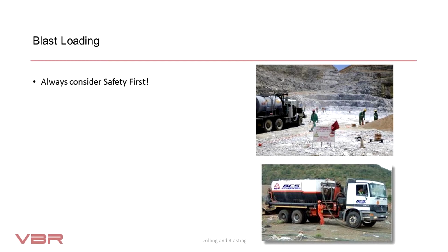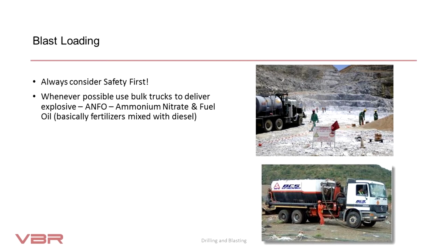Always consider safety first. Whenever possible, use bulk trucks to deliver explosive, ANFO, ammonium nitrate and fuel oil, basically fertilizers mixed with diesel. Blast as soon as possible after loading.